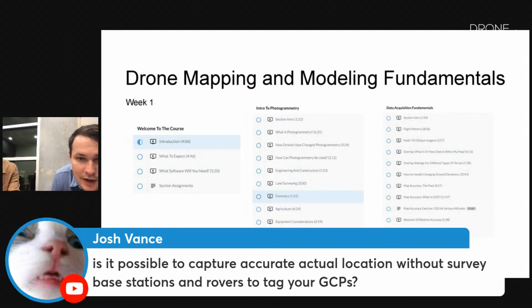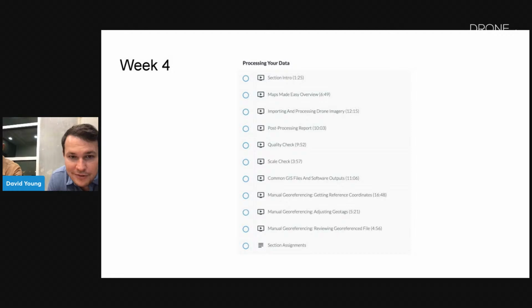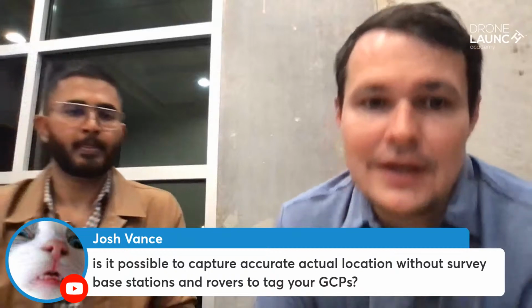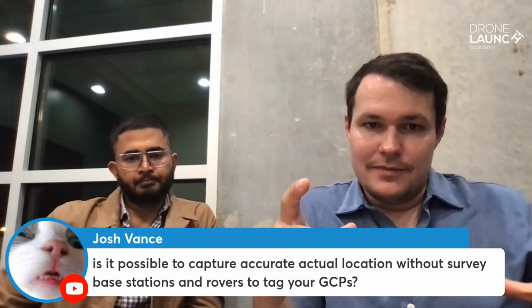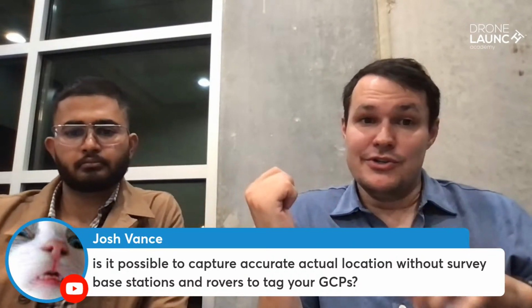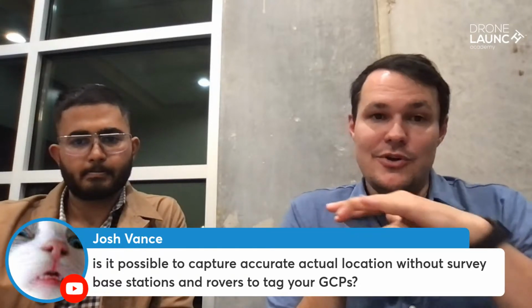Real quick too, I'm going to get in here. All right, I'm going to turn your hot thing off so I can see. Right here, in processing your data, we have 3 lessons on manual georeferencing, so putting geotags in and getting your reference coordinates. We're not saying this is going to be survey-grade accuracy, but when your map processes, at least in Maps Made Easy, it tries to pin it on the globe or Google Maps base layer as best it can, but sometimes it's off. In the course, you'll see it's off by like 50 feet. So the relative accuracy is good, but how it adjusted it on the base layer was off. But we show you how to adjust for that.